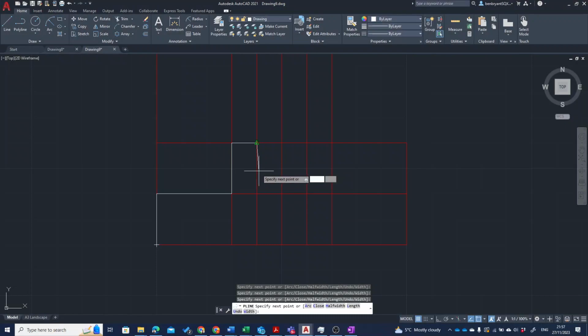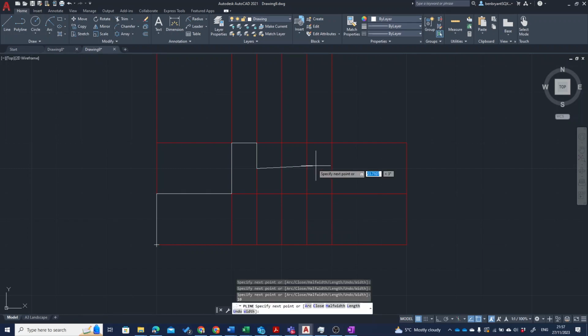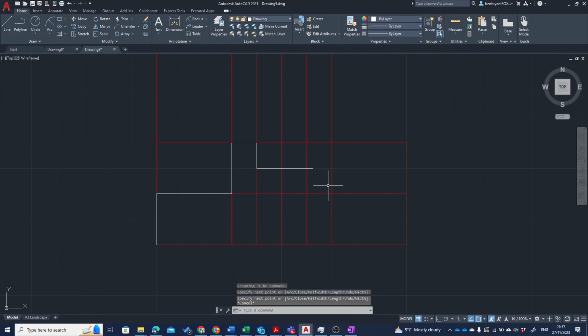I didn't put a reference line in. So what I'm going to do is latch on to a snap point. I know it's going to intersect, put 10 in. That'll then drive it halfway. And again, find a snap point, mirror off that. I'm going to pull it further than what I need it to be. Locking it to 90, hopefully. And just accept more than that line.